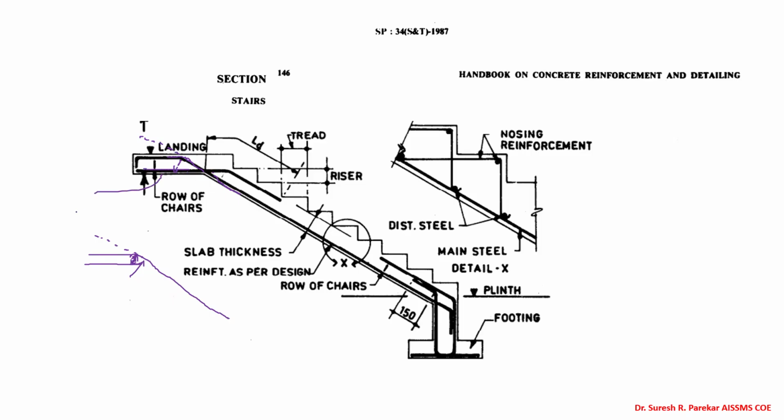So I will say we have not taken this bar below, because if we take this below, then if it tries to become straight, again you would have only cover over here. Now you can see if it tries to become straight, then you have this portion over here, and then it will not crush the concrete. And likewise, here also you can see we have not taken this directly here, because if we take it, then again, if it tries to bend, it will crush the concrete. So this reinforcement is most important in your